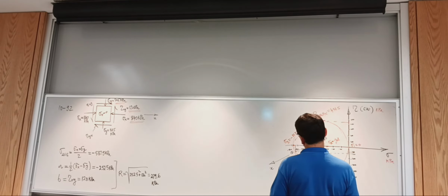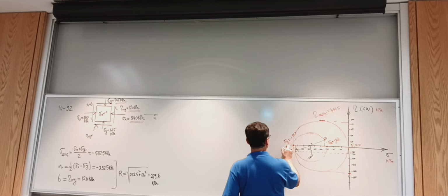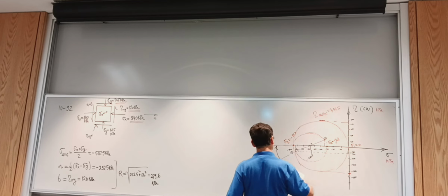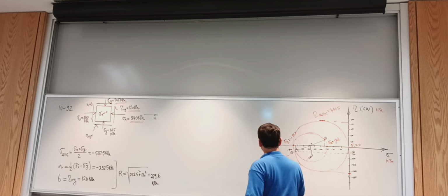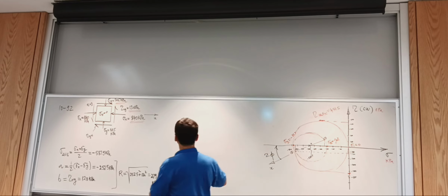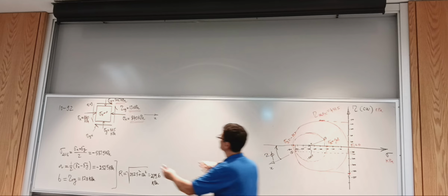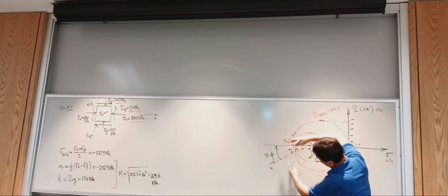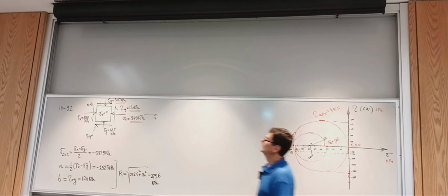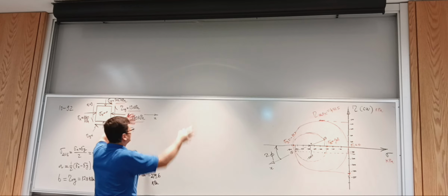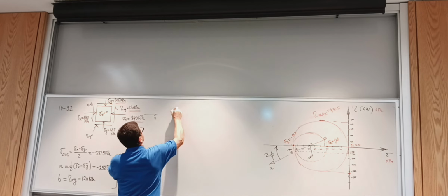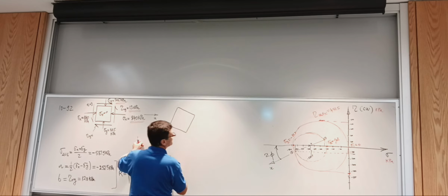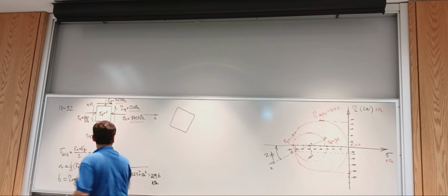So the principal element is going to be rotated. I'm looking here, so it's going to be rotated half of this angle in a clockwise direction. So this is 2 phi. And by just guessing, I need to take this element, if you can imagine, on the circle it's all flipped with the x-axis going this way. But I'm back on the element, and I need to rotate half of this angle, and I'm trying to guess it. It's probably the full angle, not half of it.